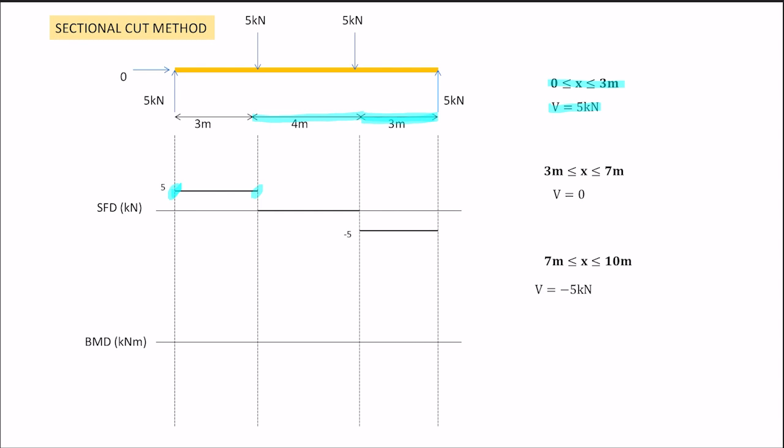That's why I said when you get V here, and you get a negative value, it doesn't mean that you are in the wrong direction. The value is negative because you are drawing the SFD. That's the reason why you have to follow. V must always be like this, and the moment you go counter clockwise. Tada! So we have our shear force diagram.